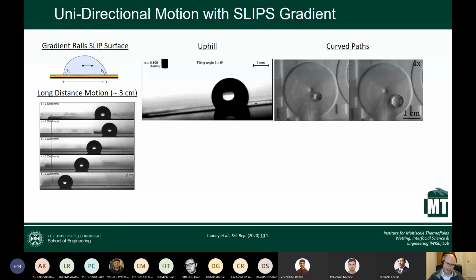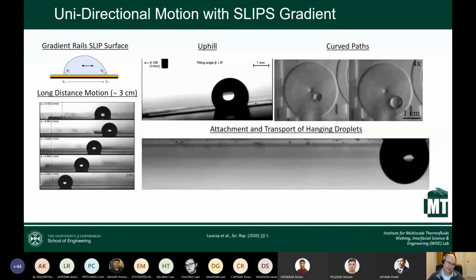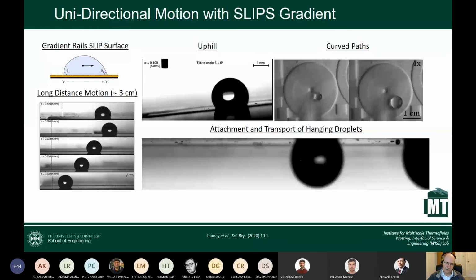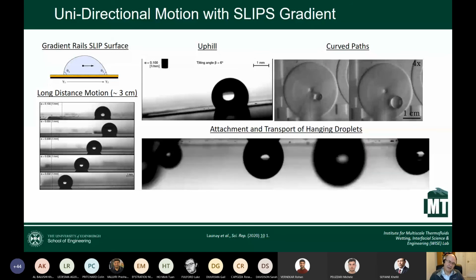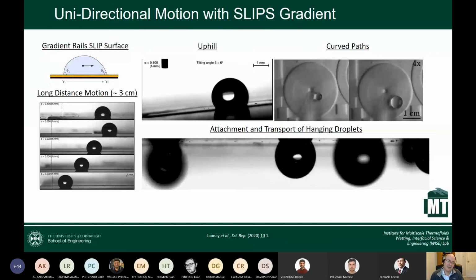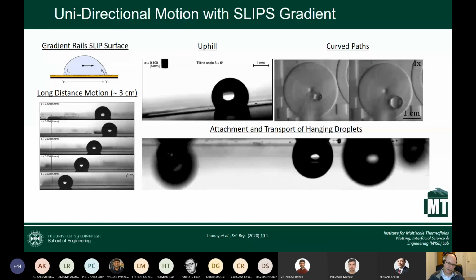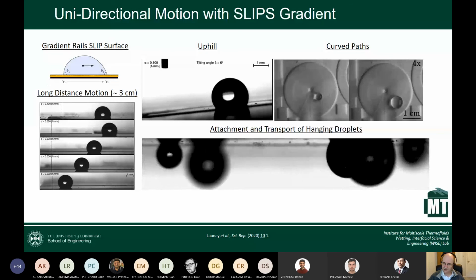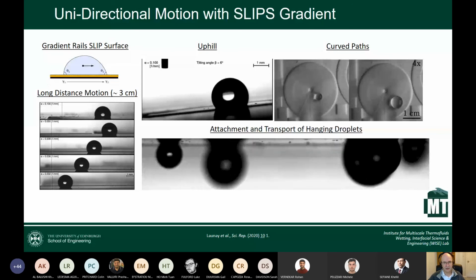In this case, they're, I think, propelled upwards using a loudspeaker, and the droplets will attach to the surface. Whilst this surface is slippery going from left to right, if you try to pull a droplet off, you can't do that. If you think about having two plates of glass, and you put a little layer of liquid between them, something like water, and you put the two glass panes together, you find it very hard to pull them apart but you can slide them apart. And so it's possible to have strong adhesion normal to the surface whilst having very easy transport along the surface. And so you get some special properties there.